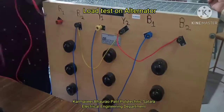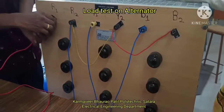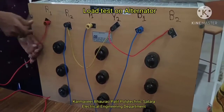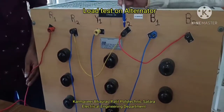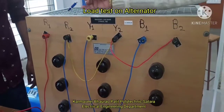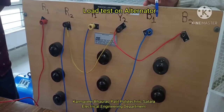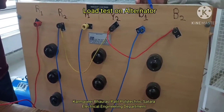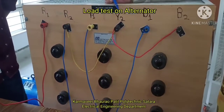Before connecting this, we will see how the load is used. You will see this is a three-phase load: R phase, Y phase and B phase. These are the three starting terminals R1, Y1 and B1. We want to make a star connection, so we are connecting R2 to Y2.